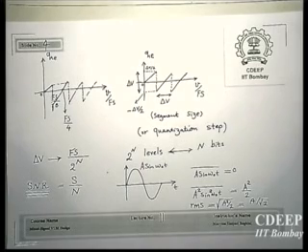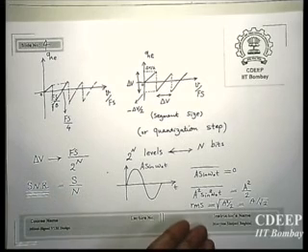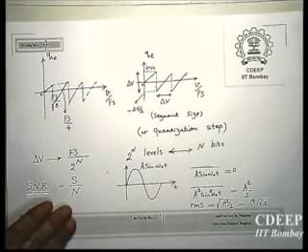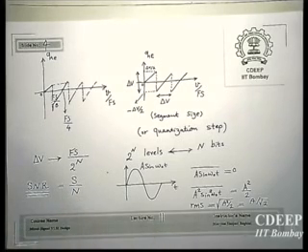Okay, so the RMS value of a signal is the effective value of a signal which could generate the same power, equivalent to this average power, if it is a constant value over time. Similarly for noise we can define the RMS value of noise, and therefore we can measure signal to noise ratio by the average power of the signal divided by the average power of noise, or the RMS value of signal divided by the RMS value of noise.